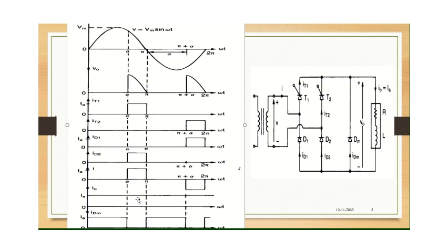is shown here as a straight line. But mind it again, in the beginning I had told that all the working assumes that the current is continuous. For your information, because the load is RL type, the current will not be a straight line like this. Whenever the semiconductor device T1 is turned on and you are getting output, the current will gradually increase at this point. And during this period it will be slowly, gradually decreasing. Why? Because of the inductive nature. Because the energy stored in the inductor will now be flowing in this circuit, right?